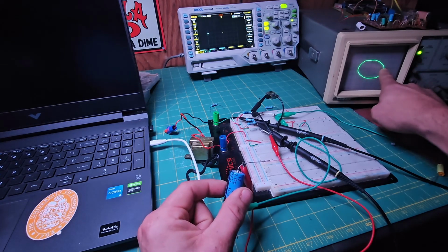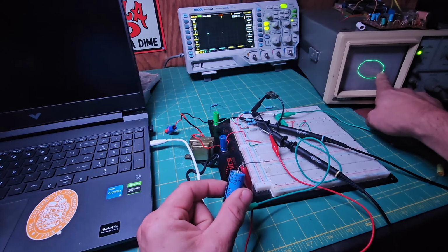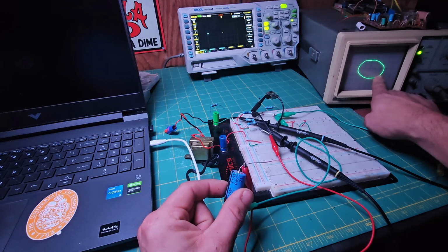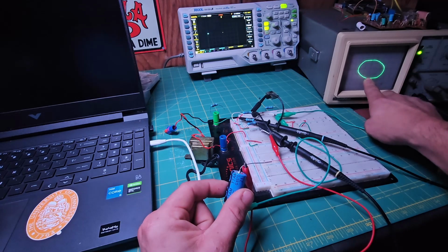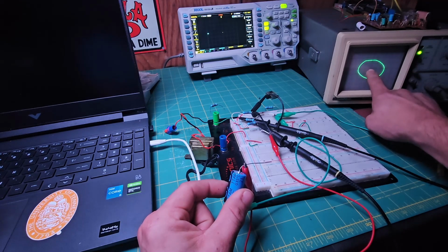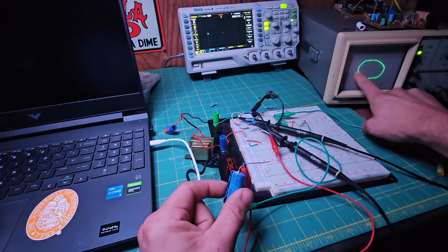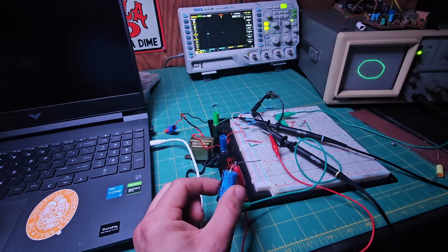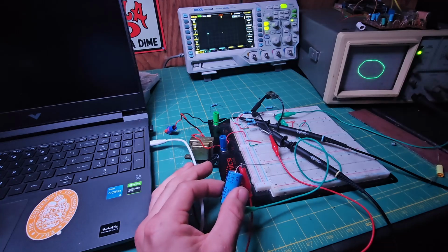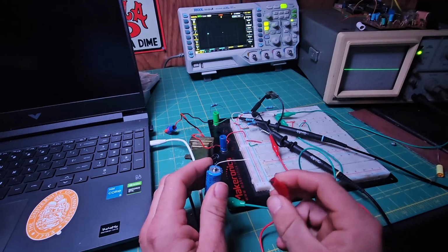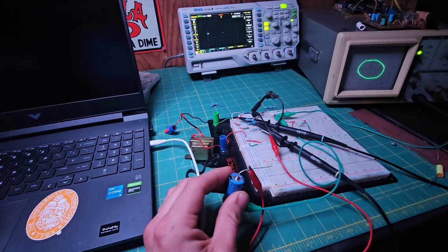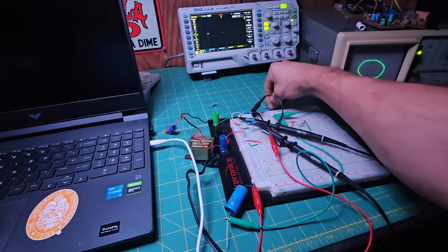And so at zero, it's not going to flow any current. Then the voltage begins to drop across it, and it wants to provide current to prevent that from happening. And so you get this outward current here that peaks in the same fashion. It peaks where the sine wave is zero. And then it comes back and it comes full circle. So that is why a capacitor would draw an oval on that, and a resistor would just draw a linear line.